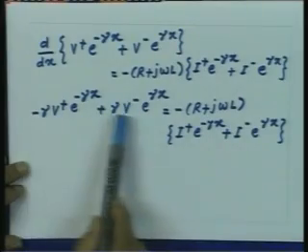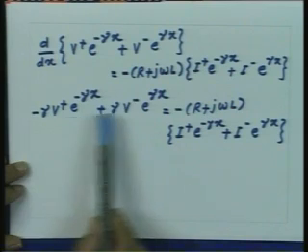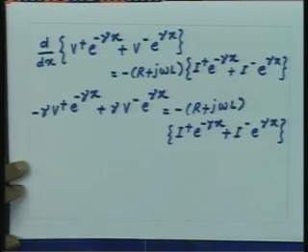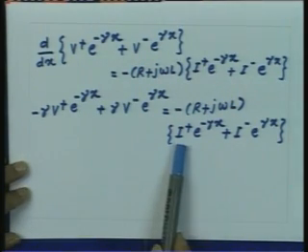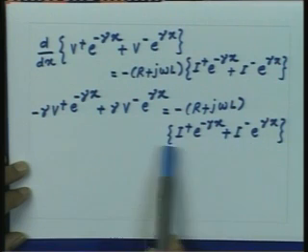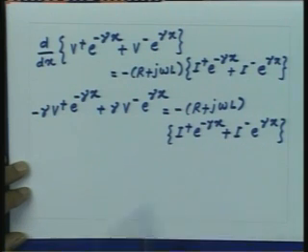At first look, it appears that there is one equation which is relating the voltages and currents. However, if you look at it a little deeper, you will notice that the V plus and V minus terms represent two waves which are travelling in different directions. Similarly, the I plus and I minus terms also represent current waves travelling in two different directions.